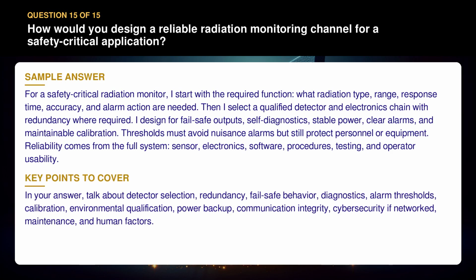In your answer, talk about detector selection, redundancy, fail-safe behavior, diagnostics, alarm thresholds, calibration, environmental qualification, power backup, communication integrity, cybersecurity of networked systems, maintenance, and human factors.